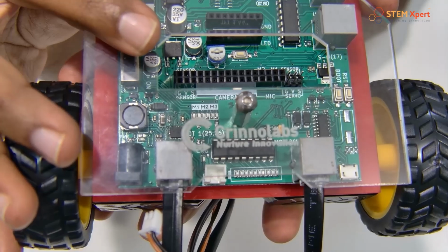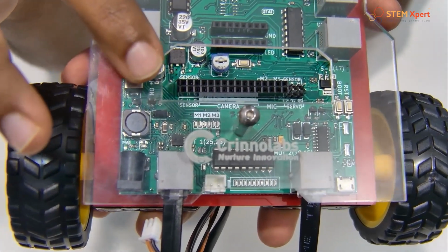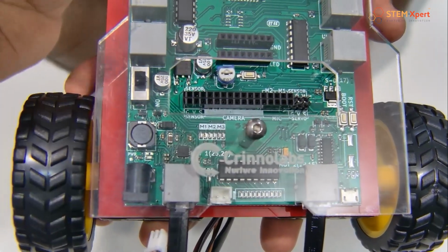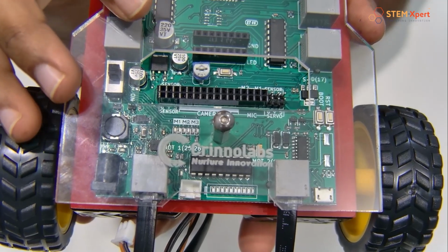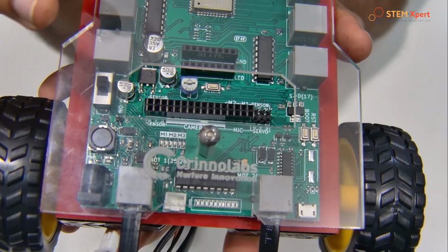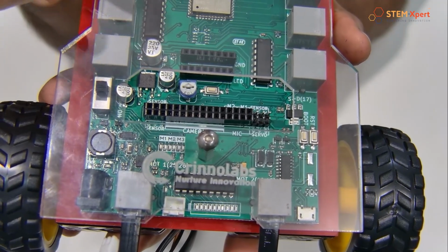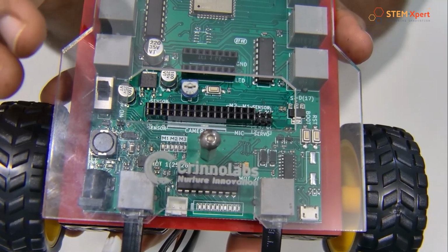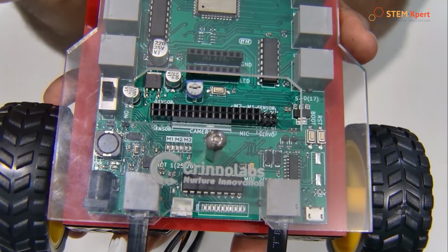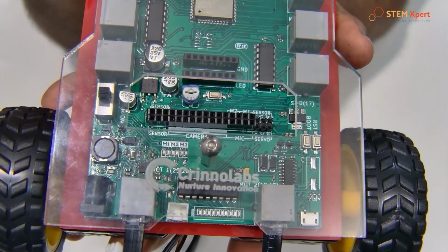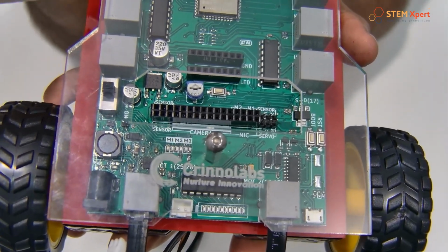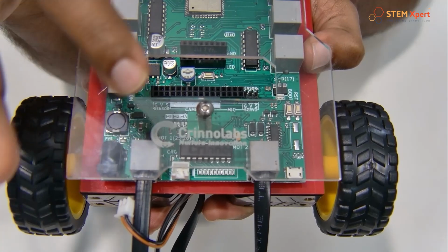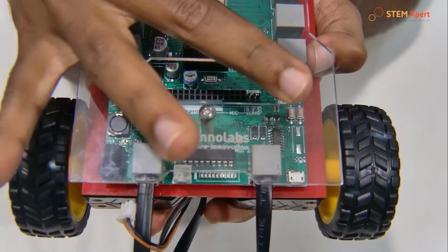When you have a look at this board, you can find M1, M2, M3 over there, right? There we can have 6 LEDs in total. These pins are used for connecting the motors, and the motor pins are 25, 26, 19, 15, 32 and 33. These 2 RJ11 ports are used for connecting these 2 motors.